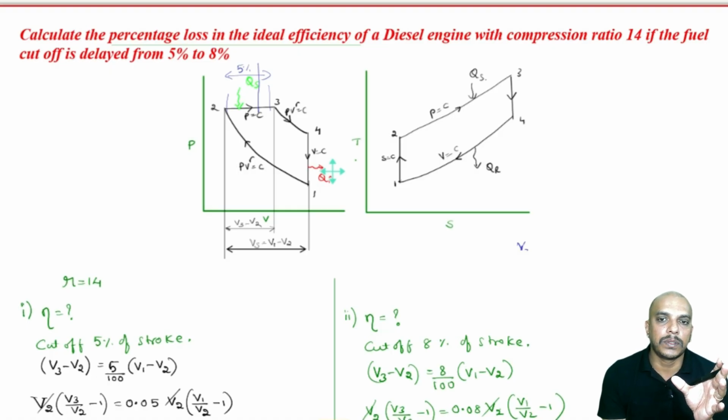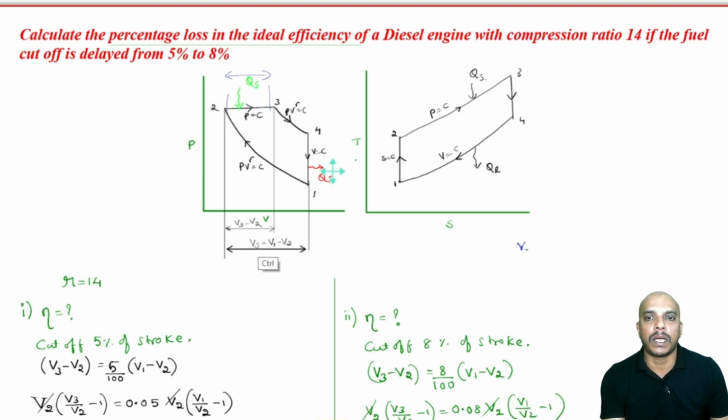Why, we can think of it like this. This is a portion about which we are compromising on expansion. If you keep on supplying the fuel for the remaining stroke, where do we give some time for the combustion products to expand and do the work? So, we cannot go on increasing this value. Heat has to be added within that small portion of volume, that will give us the better efficiency. And this can be told mathematically also.